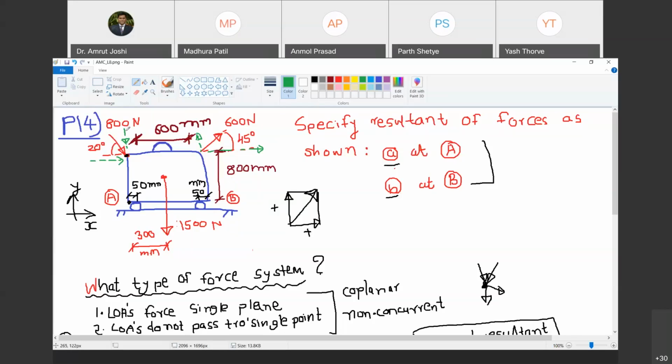Now let us say I have to find out moment of vertical component of 800 newton force at A. तो वो कितना आएगा? सो इसका जो लाइन ऑफ एक्शन है उसके ऊपर मुझे ए से परपेंडिकुलर ड्रॉ करना पड़ेगा. And as this line of action passes through A, it does not produce any moment. Do you agree with me? Yes, sir. देखो, जो कि ये 800 न्यूटन का फोर्स है वो ए पॉइंट में से ही पास होता है. सो हाउ कैन इट प्रोड्यूस एनी मोमेंट अबाउट इट? इट इज नॉट पॉसिबल. Perpendicular distance between A and line of action of 800 newton is zero. Happy? Yes, sir.